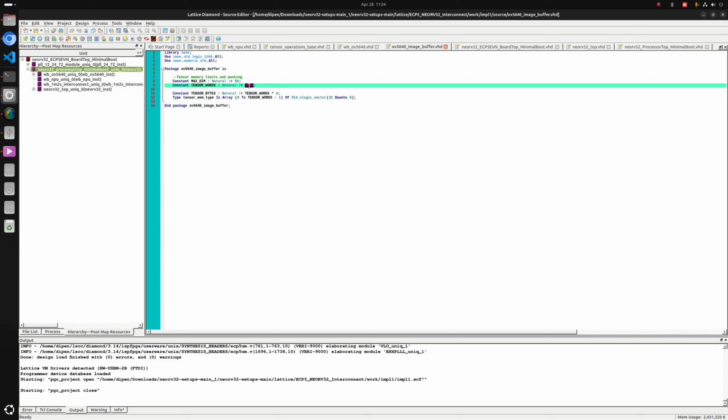So the largest image we can store is 100 by 100 grayscale, in which each pixel is about 8 bits. You can change this value depending on your VRAM block availability or your application. For example, if we didn't have the NPU, we could have changed this value to be much larger, and captured 200 by 200 grayscale images, etc.